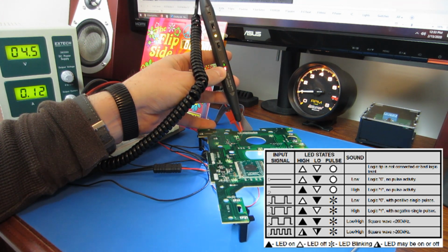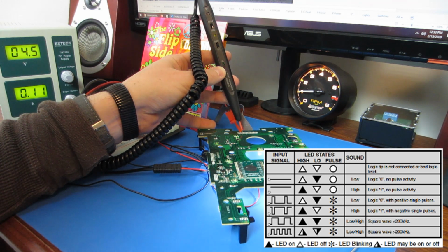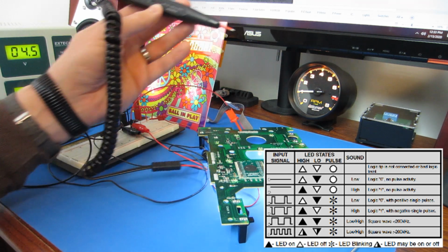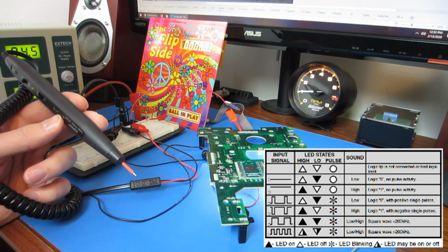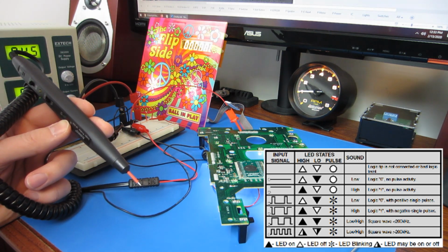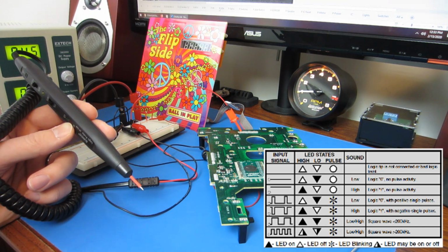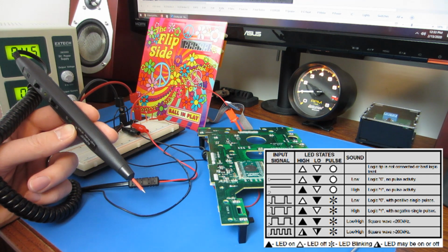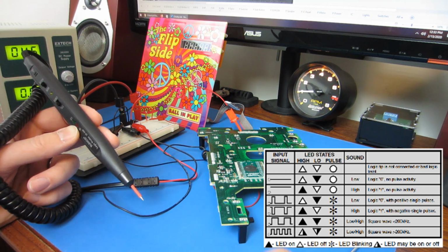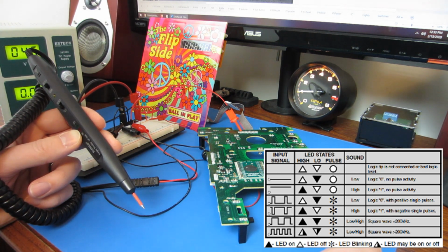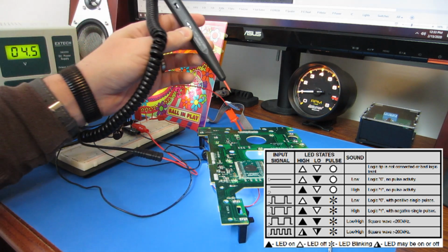So it's pulsing, maybe slowly. It's interesting that that's pulsing to me. So chip select is used when you have multiple slave devices in a circuit being controlled by a single master. The master has one chip select trace going to each of the slaves, and the slave that it wants to talk to, that it wants to command, it will set the chip select low. So I was kind of expecting this chip select to always be low, since it's only talking to one slave, but it looks like it's pulsing.